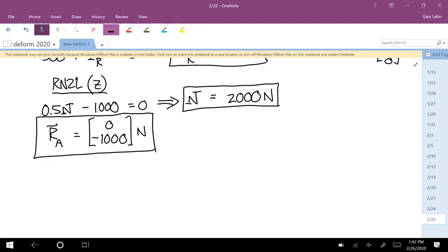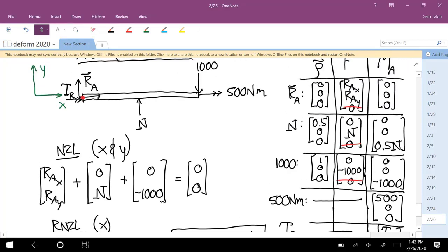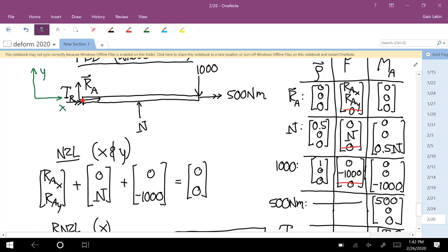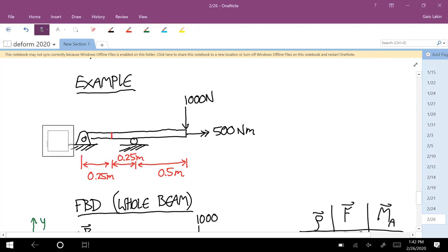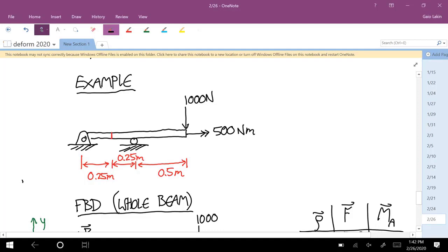So that's sort of an interesting thing. In order to have rotational equilibrium met, even though in a sense these are resisting a downward force, you might think that they'd both be applying upward forces. The way it's going to have to work is that that pin is going to have to pull down on this member to keep it from rotating.